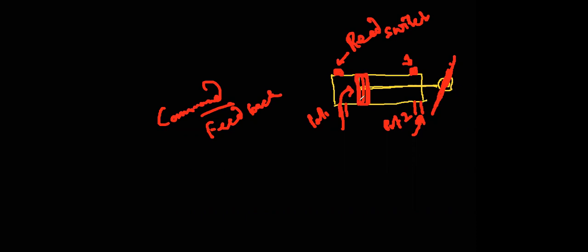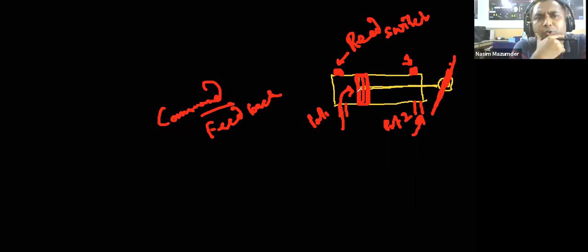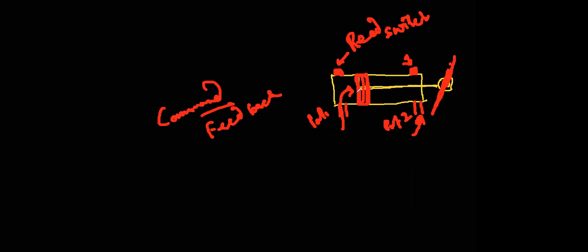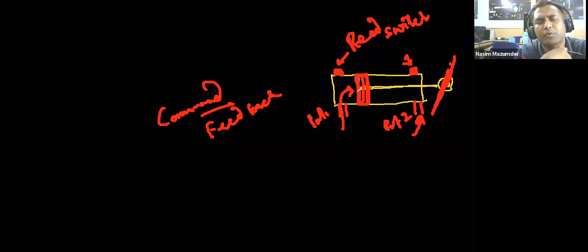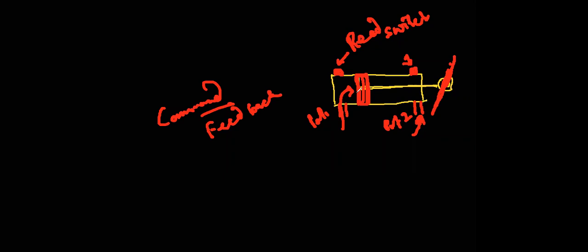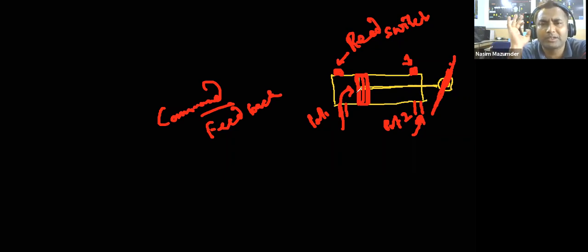So this concept of switch or this feedback, this comes with on-off valves also. Not the reed switch, but this feedback one. Yes, exactly. If you are using any kind of field devices, and you want to know the position whether it is on or off, you need some feedback from the field. Now reed switches are specifically used for power cylinders. So how does this reed switch work?